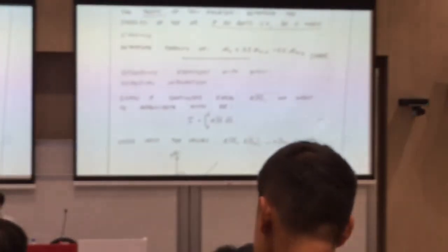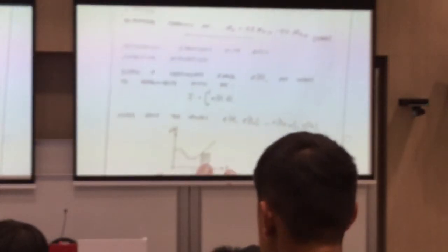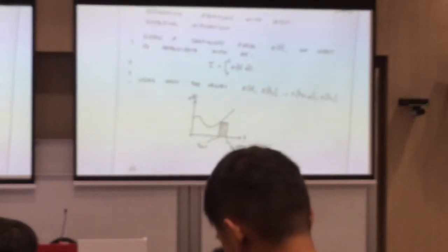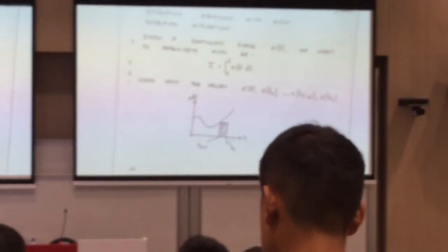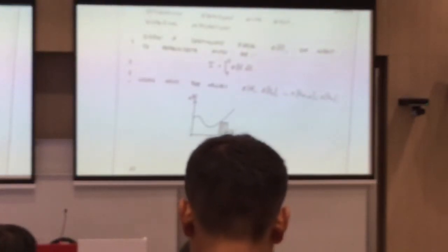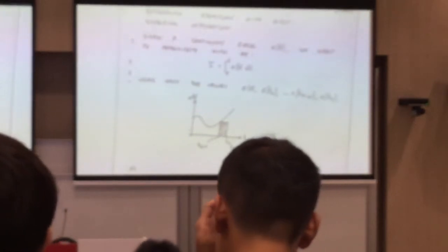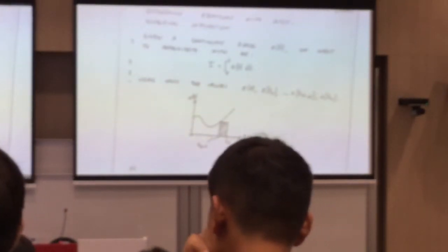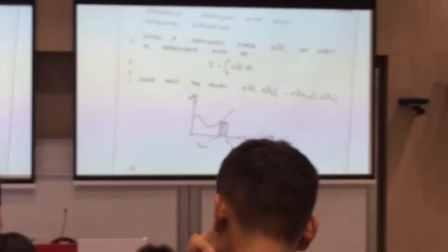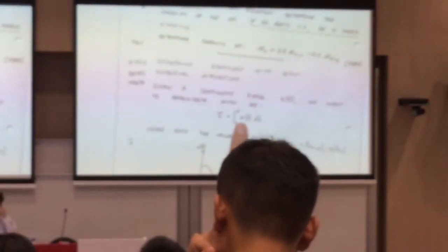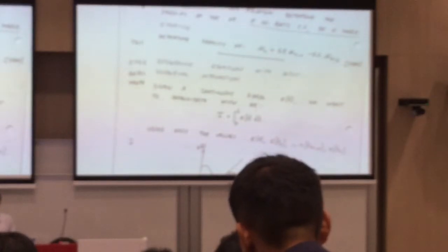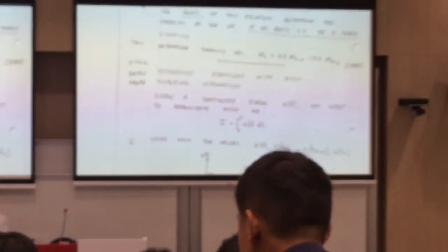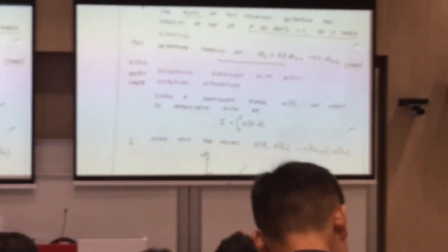So after we talk about the differentiation, then we talk about the integration. Differentiation is approximated by a difference equation, x(k+1) minus x(k). Then your integration will become a summation. So if your output is an integration of your input, then basically you can use similar things like forward rectangular, backward rectangular, and trapezoidal. Okay? So this is how to do the approximation.